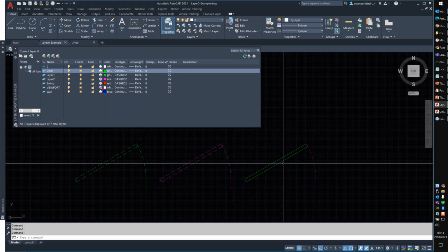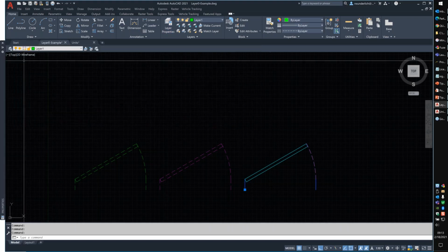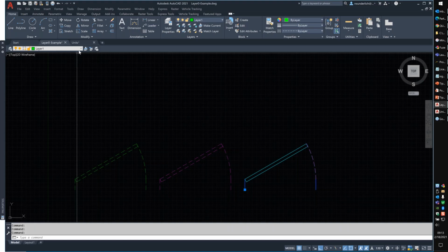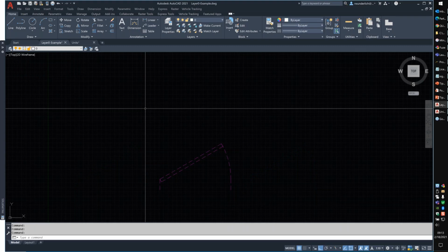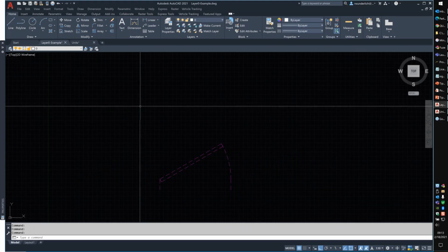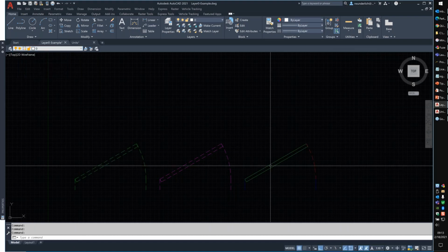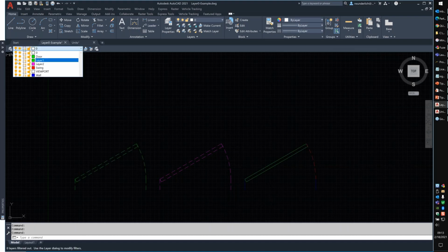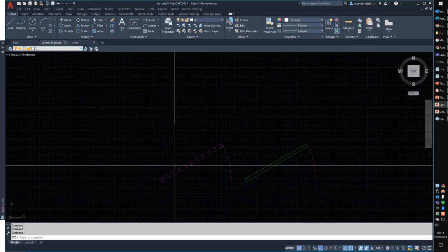And if I click on this block, you're going to see that this block here, and we're going to play with this, is drawn on layer 1. And if I freeze layer 1, that door disappears, even though the geometry is not drawn on layer 1 because it's inserted there. If I turn layer 1 off, it does not disappear. So sometimes, depending on how you use freeze and thaw versus on or off, which again is the next component of this webinar, will show how this manipulates.